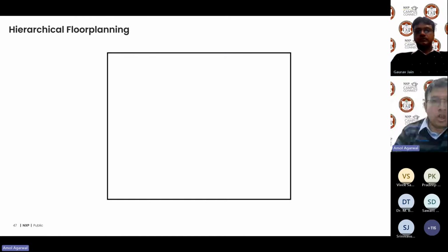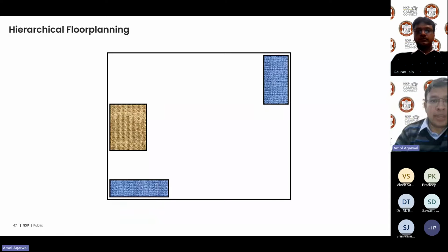So now again, we will see what floor planning is. In floor planning, as we discussed in the earlier part, you would have two sort of things. One is your full custom design, where you have, say, analog blocks, memories, analog PLLs. These would be your hard macros, which you would fit into your floor plan. So suppose there is a square floor plan. This is a very ideal floor plan.